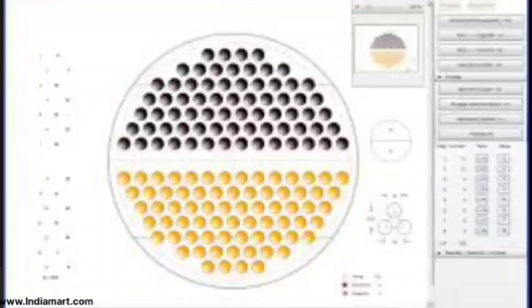Also in PV Elite, when you calculate or look at the reports, they mention the clause there, which UW they are using and what thickness they are using to arrive at it. By referring to that, you can find how the fillet thickness is arrived at.